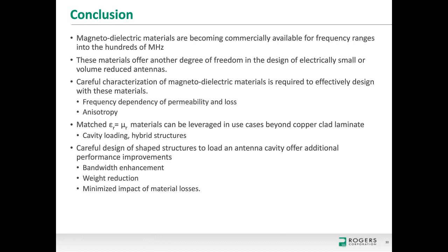First question, ferrite is normally gyrotropic, and dielectrics are anisotropic in substrates. How do you account for these effects, especially for ferrite containing magnetodielectrics? The key that we've found is generally to characterize them in multiple axes. So looking at both the combination of an airline measurement and a resonant measurement method. The gyrotropic nature of the materials, we are currently evaluating methods of characterizing these materials under bias fields. But generally, when you're putting these materials into a composite structure, you're reducing the impact of some other changes because you're averaging the magnetic material or the ferrite's properties with the properties of a polymer system.